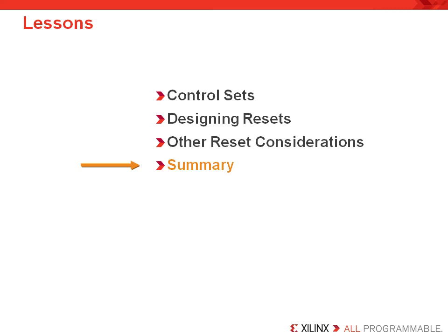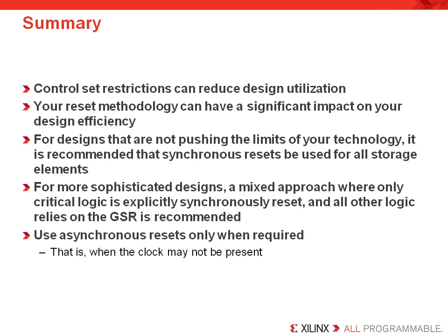Now, let's wrap up our control set discussion with the flip-flop resources with a short summary. In summary, control set restrictions can reduce your design utilization. This prevents all of your flip-flops from being merged into the same slice and can restrict some slices to holding fewer registers than might be possible. Now, your reset methodology can have a significant impact on your design efficiency, especially if you choose an asynchronous reset, because this can reduce, again, your device utilization, increase the number of routing resources that is used, which may also impact the speed of your finished design.